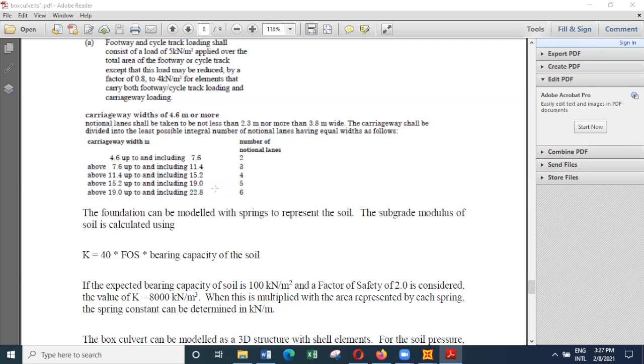And then all the soil pressure will act in the middle. So because of that, this bottom slab can bend upwards. So you have to have sufficient thickness to make sure that these bending stresses are kept at a lower level. So because of that reason, generally the bottom slab thickness can be higher than the top slab thickness.